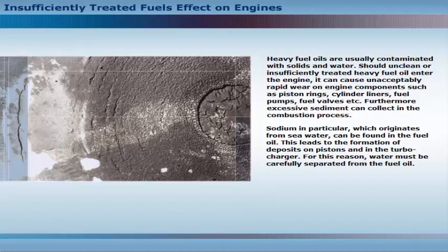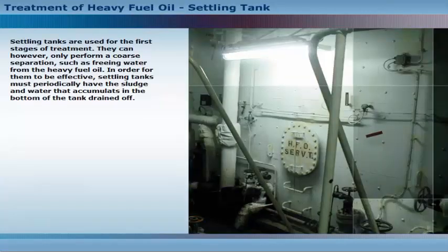Furthermore, excessive sediment can collect in the combustion process. Sodium in particular, which originates from seawater, can be found in the fuel oil. This leads to the formation of deposits on pistons and in the turbocharger. For this reason, water must be carefully separated from the fuel oil. Settling tanks are used for the first stages of treatment.